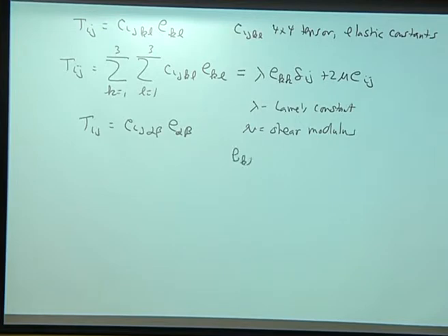Ekk, remember you sum over, so it's equal to e11 plus, it's the sum of the strain. Basically, it's the trace of the strain tensor. And I won't go through the tensor contraction. So if you wrote out Cijkl for an isotropic material and you went through all the contractions, that's what you'd end up with. Okay. So equilibrium.